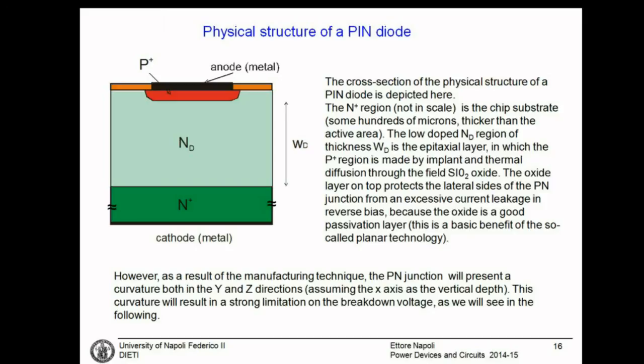This is the structure, but we now see that this structure has some differences. The P region here is curved. There is a curvature here. And in reality, if I think of this structure in the 3 dimensions, I will see that this mask in the Z direction will cause some spherical borders, curved borders that also have an effect on the behavior of the device.